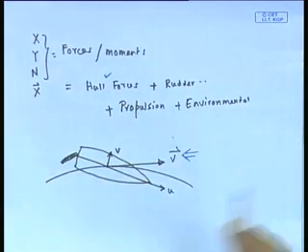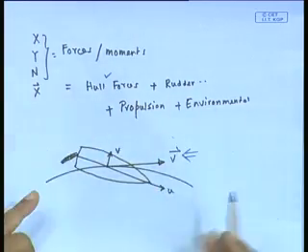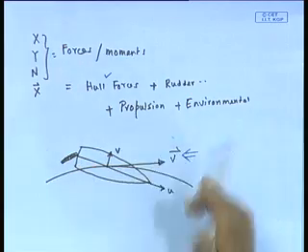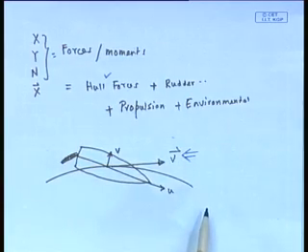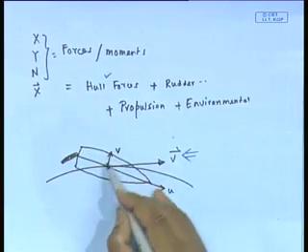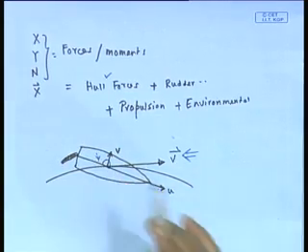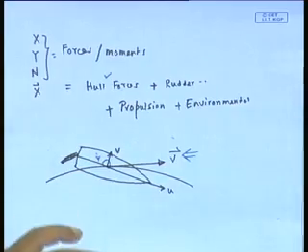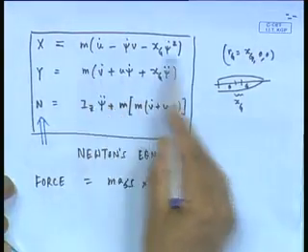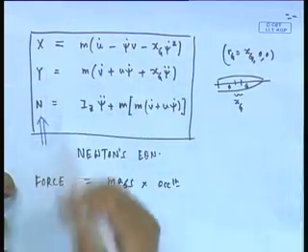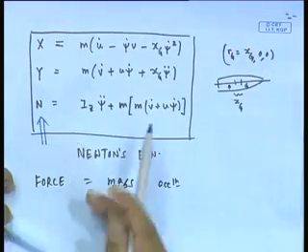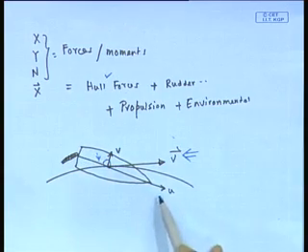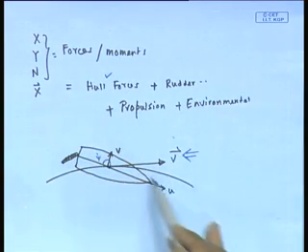Now, of course, here I am trying to figure out all force components that arise. Remember, this is a situation where the body is undergoing a motion, it has certain u, certain v, maybe certain psi dot. So, all these are my inertia forces on this side, and they should balance with my total force acting on the hull. What are the total forces? First of all, I have forces arising on the hull because the water is flowing this way.